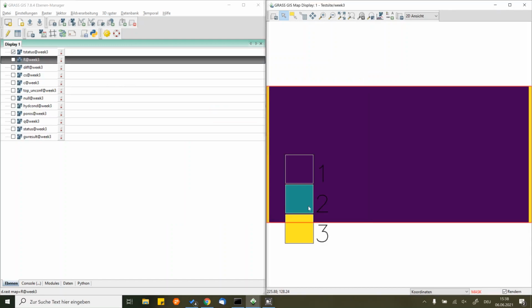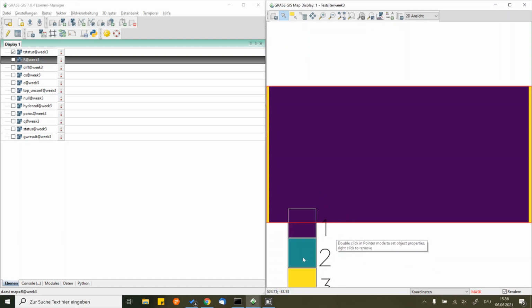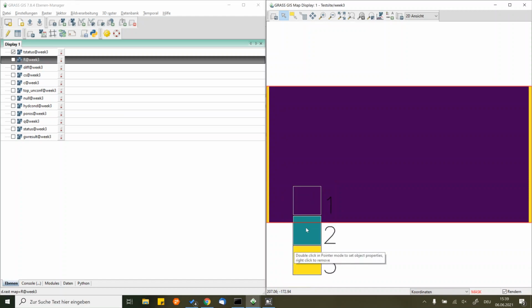You will see here that we have a 3 on the left and right, which is defined, if you follow the man page, as transient boundary conditions, but that just means Neumann boundary conditions, so the tracer can flow out to both of those boundaries, and we have no flow boundary conditions on the left and right. So very much similar to the flow module, just we do not have Dirichlet boundary conditions on left and right, but these transient boundary conditions on left and right. And this is already it.